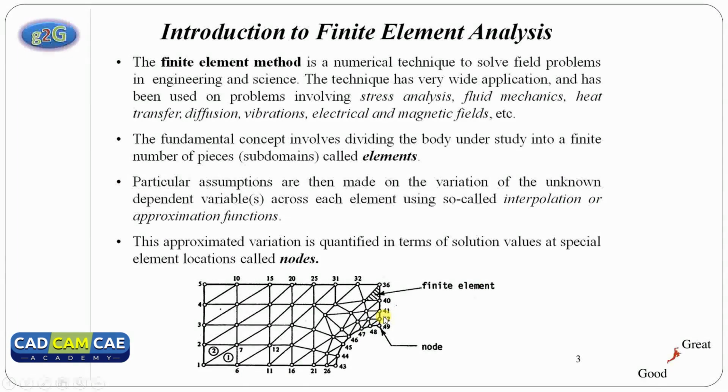In any body, by using finite element analysis and applying the boundary conditions, that is, by applying the force, it is possible to obtain the displacement of each and every node, and the stresses are obtained on each and every element.